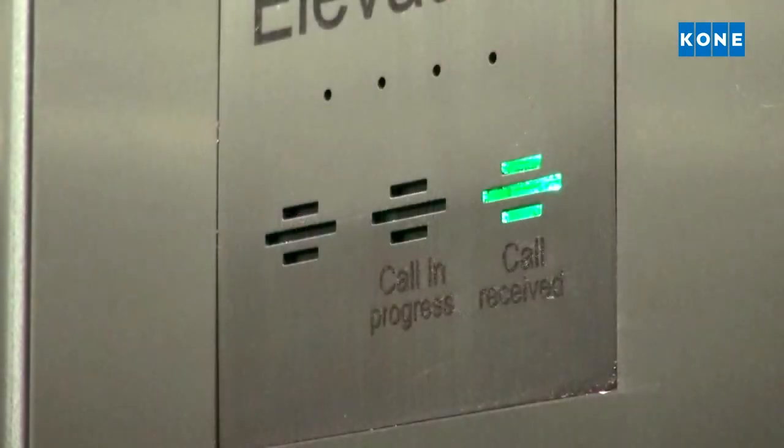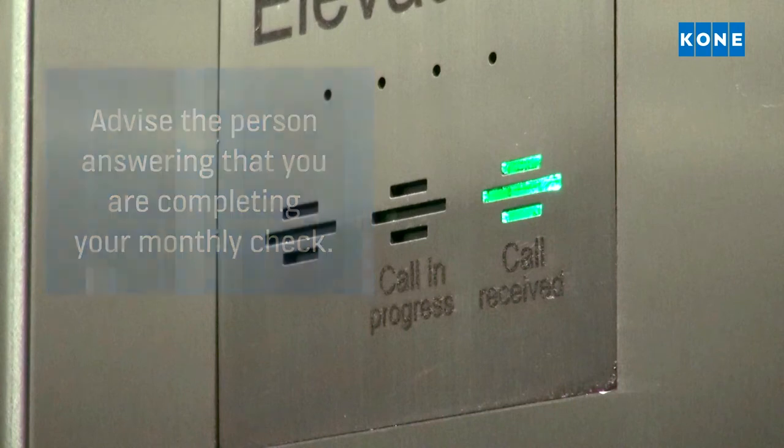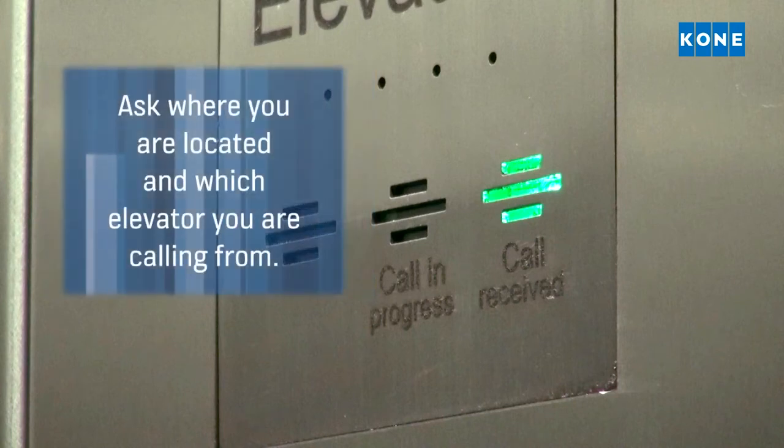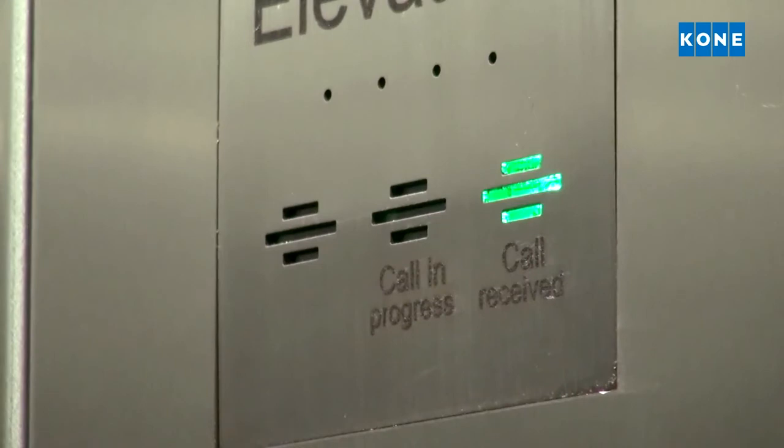Once the message has played, you should advise the person answering the call that you are completing your monthly check of the elevator emergency phone and ask the person on the other end where you are located and what elevator you are calling from to confirm that their information is correct. Once completed, the phone call ends and the emergency phone will automatically time out and reset.